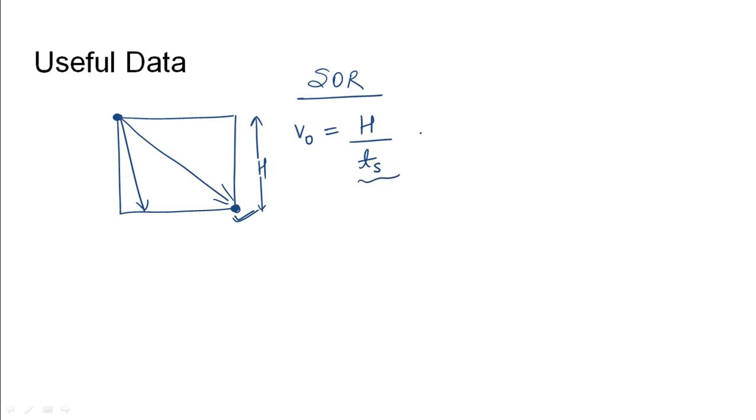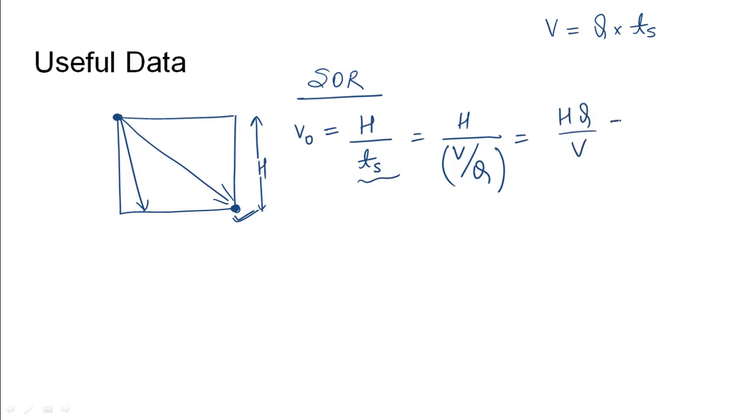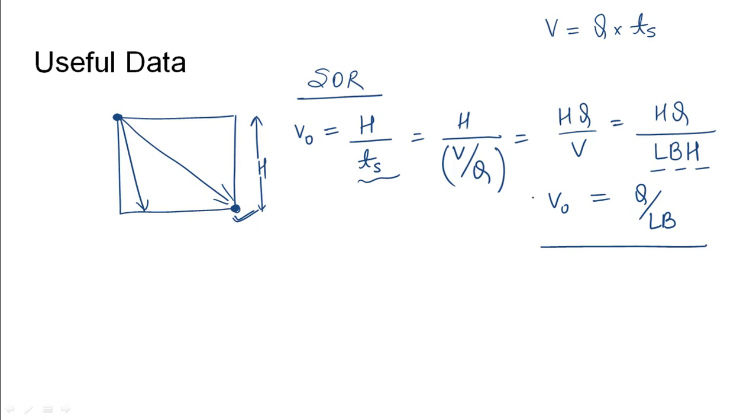This settling time should essentially be the same as the volume of the tank divided by discharge, as we will process V volume of water at the rate of Q in TS time. So TS will be V by Q. This can be written as HQ over V, and V is nothing but the volume of the tank. Since it is a cuboidal tank, we can assume it to be length into width into depth. This would give surface overflow rate as Q by B into L. It is called V naught.